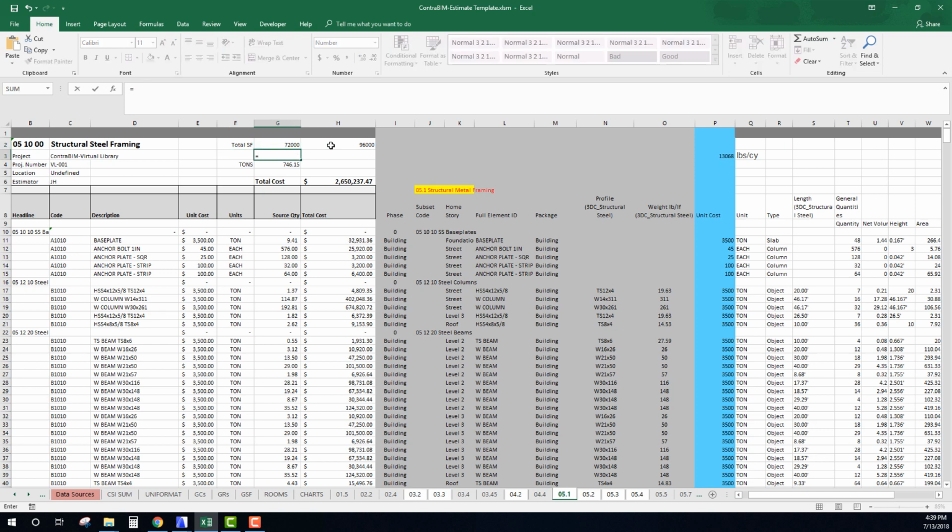And so here, let's just do our tons divided by our square footage, and we're actually going back to pounds. So this is pounds per square foot. So 20. That might be a little heavy. Let's try this again though. If it was supposed to include our ground square footage times 2,000. Okay, so that actually puts us right in that range of 15,000. So I think that might actually be the number we're supposed to be using for total gross square footage in terms of pounds per square foot on total project.